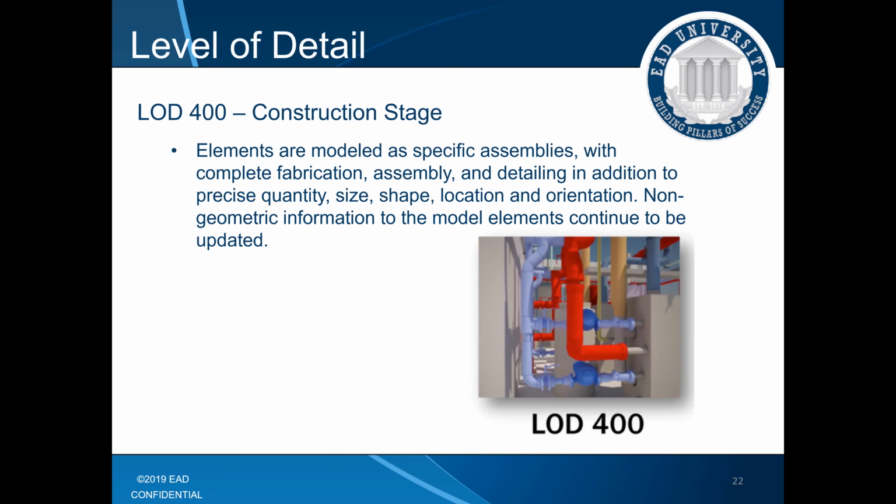I think it's important to note that during the LOD 400 stage, when we send a structural package out to a vendor, they can take our drawing, and if you have an LOD 400 level of detail in your drawing, like the bolt holes and coping on the flanges, that will actually be shown in the model, and they can integrate that within the software they use to cut their beams and assemblies.